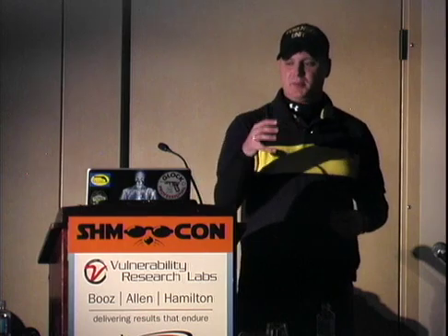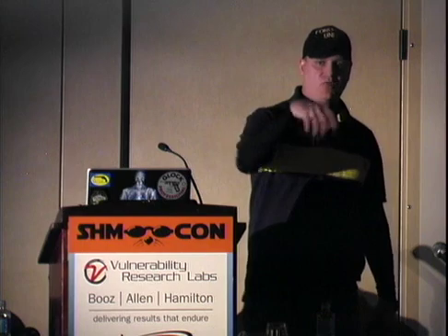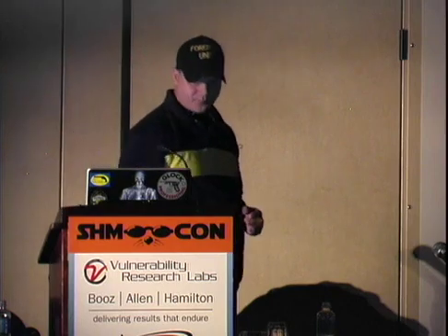Now, the exception to this is that some of the newer Seagate and Western Digital hard drives that are now in little mini towers and standing up on their end, and you jiggle the table and they go boom, right? Now what happens actually is that the platters are so heavy, in a lot of cases the spindle will break free. And the spindle inside the drive will not turn anymore at all. So if you open up the drive and you're not able to turn it at all, and the platters don't spin at all, then your motor is seized, and that's a more advanced replacement at that point in time. But if it does turn at all, and you can break the head free, you will probably be able to read your data and do okay.